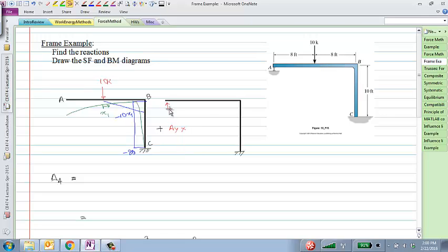So if I apply a unit moment here, it would of course bend up. I'll draw that too, something like that. In this case, the bending moment diagram, I'll draw it in red, and you'll see in a minute why. I'll draw it as positive, increasing linearly all the way up to there. I'll call that point X, and that would be positive 1x. And at the end, it would also be a positive moment of this 1 times this entire 16, which is 16 kip feet. So these are the two bending moment diagrams that I have.